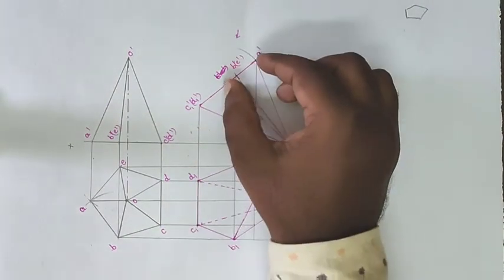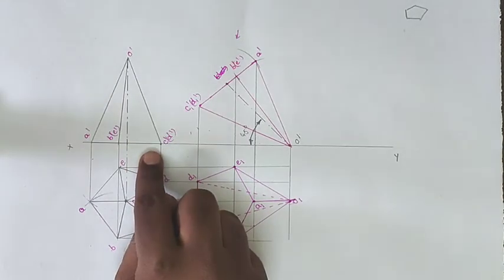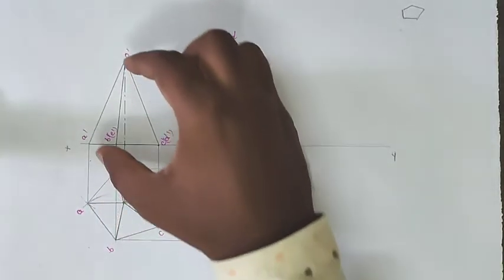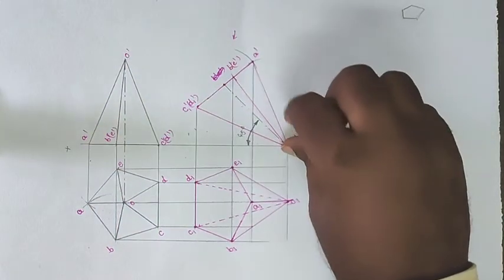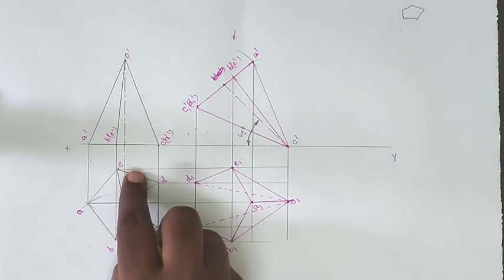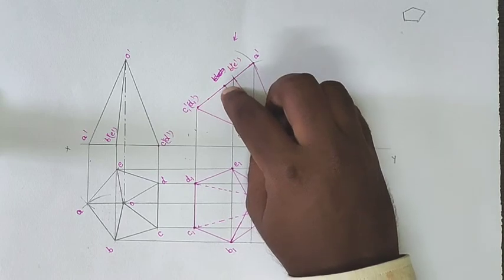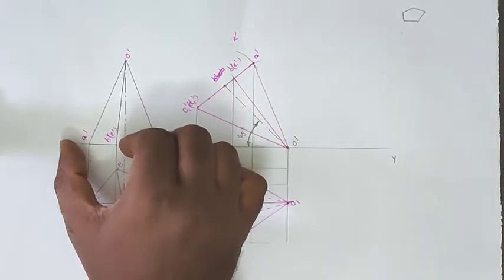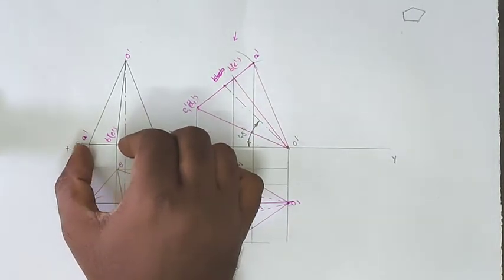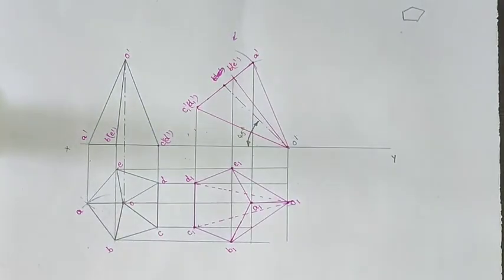After that we will draw the base of that front view. So for that I am measuring the O dash and A dash line length. From O dash I am drawing the arc. After that measuring the center of that axis line, from the other end of the axis line to the distance of that A dash. With that distance I am cutting that arc and locating A dash.